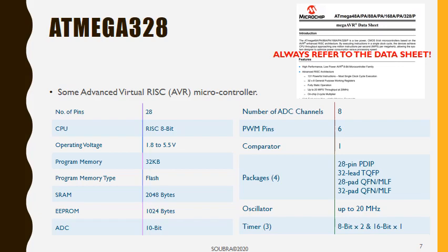What about the EEPROM? I'm going to give you a hint. The first two letters of an EEPROM are electrically erasable. What does it mean? When I power it off, what would happen to the user data that I'm saving in there? Poof? Or do they stay? On power off, they stay. However, you can erase them, and you need to apply some voltage in order to erase them. So it's controllable. The default thing is they're still there if I don't erase them.